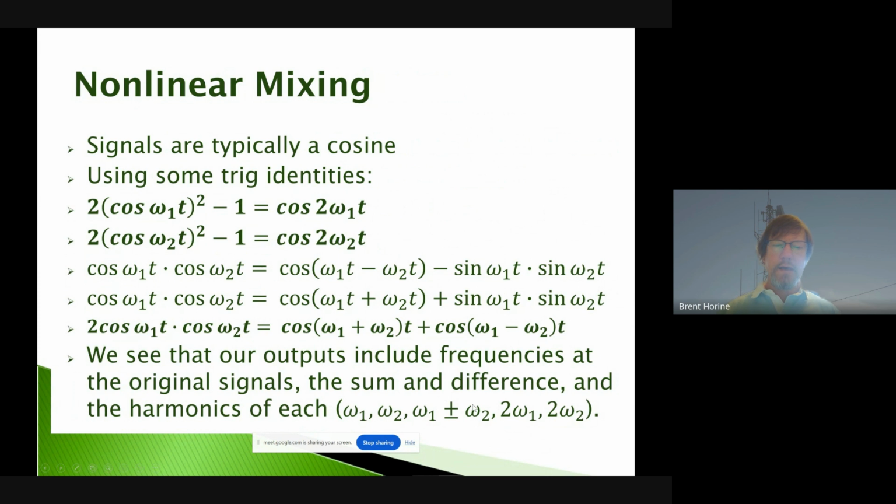So a very important principle. Again, I think it's fun to work through this trigonometric process. You can do it through this Fourier transform translation property also, and that's probably a lot simpler. But I like the idea of looking at why this nonlinear thing, when we multiply, actually gives us a multiplication and these translated frequencies.